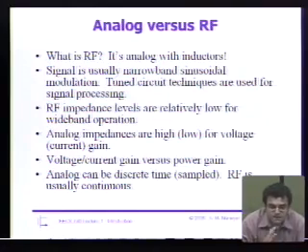In other words, I can sample my analog signal, and I only care about those samples. By the sampling theorem, we all know that we can reconstruct a band-limited signal, and so I can process my signals in a discrete time fashion. That's a big distinction between analog and RF, and we'll take advantage of that in this course. Questions or comments?